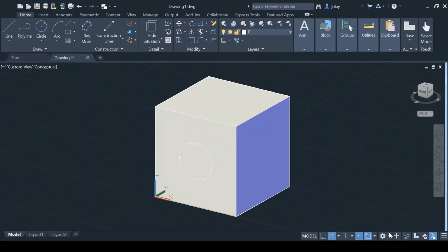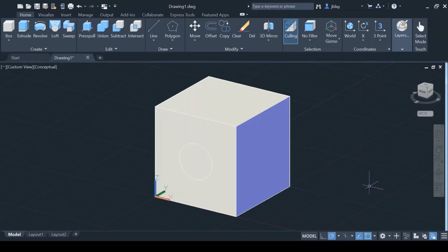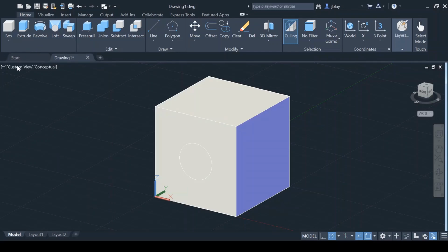If you go over to your 3D Basics ribbon, you'll see that here's extrude, but we really don't have an option for intrude anywhere. None of it is intrude. What we need to use is a command called press pull, which presses or pulls a bounded area.